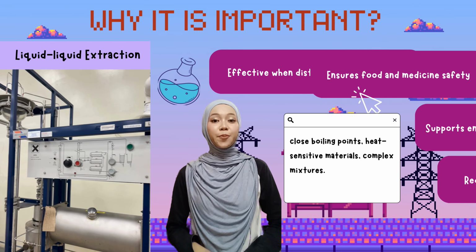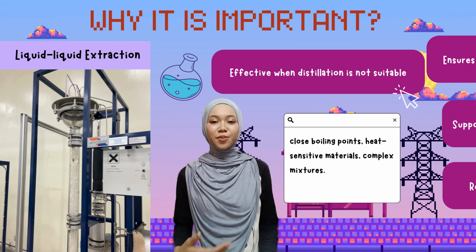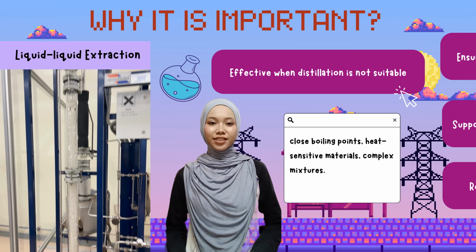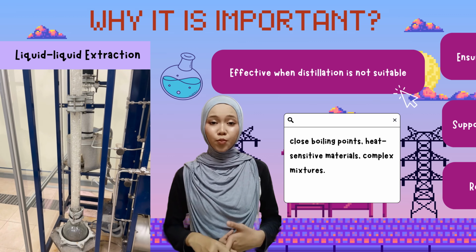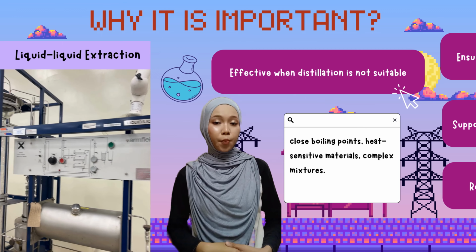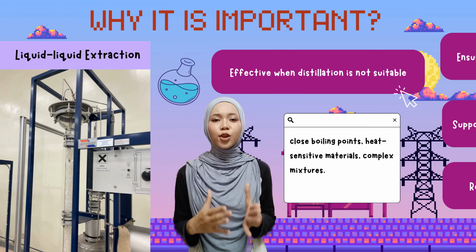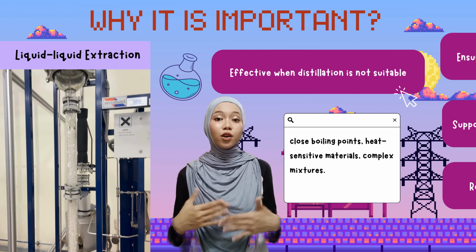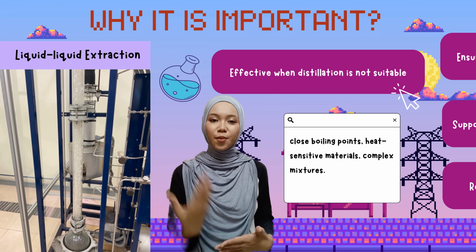Liquid extraction is important because some mixtures cannot be separated using distillation. When substances have very close boiling points or are sensitive to heat, heating may damage the product. In such cases, liquid extraction provides a more suitable and effective separation method.